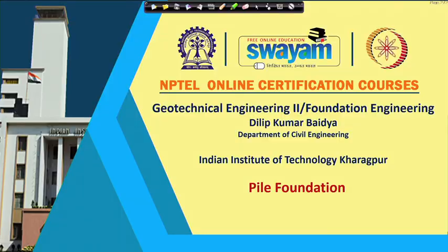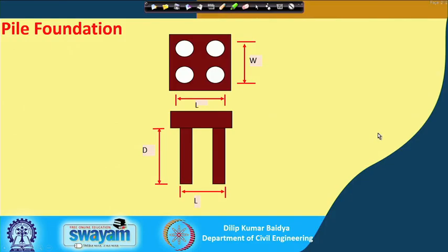So, that part I will take, and then finally I will take a numerical problem of a pile group: based on individual pile failure, what could be the capacity, based on block failure, what could be the capacity, and finally, what could be the recommended design value of the pile capacity. So, first let me take the first slide, which shows how I can consider the group.